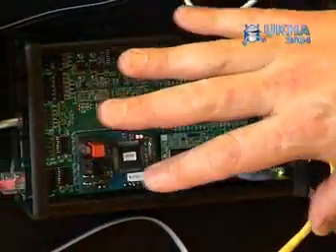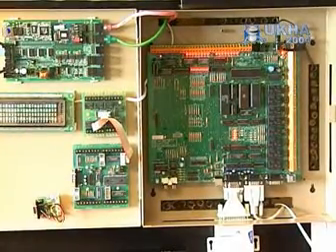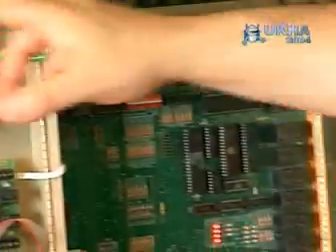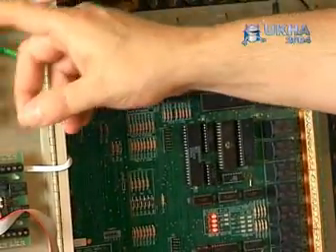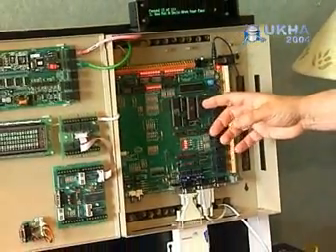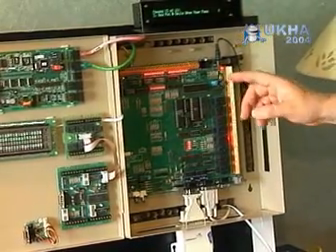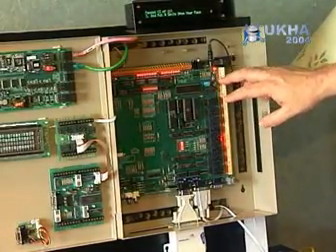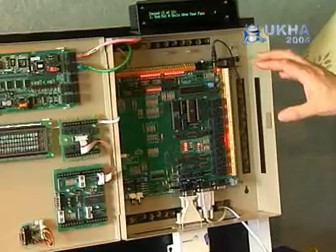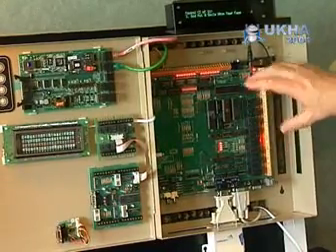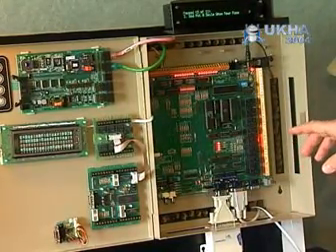We then took that concept and used the same hardware, created another board here, which again connects to C-Bus on one side and comes out of there and straight into Home Vision on the other side. So this board again deals with all the C-Bus interaction and gives messages back to Home Vision to allow Home Vision to react to C-Bus changes or indeed Home Vision to control C-Bus. This requires a new ROM that runs in Home Vision that we've coded, which is version 3.4, which will be available shortly. And the beauty of using a hardware solution is all of the C-Bus processing is offloaded from the Home Vision Pro controller, allowing it to run faster and more efficiently.